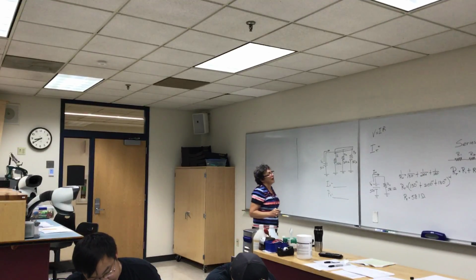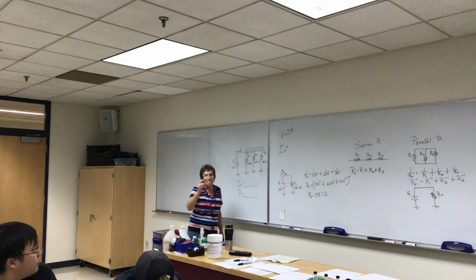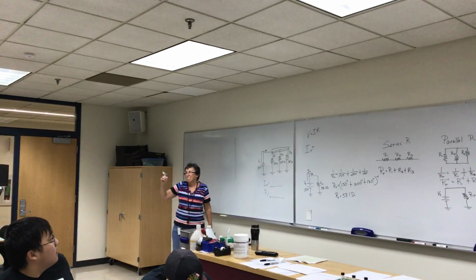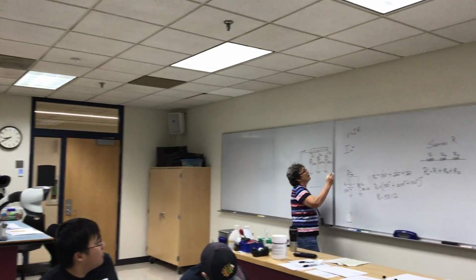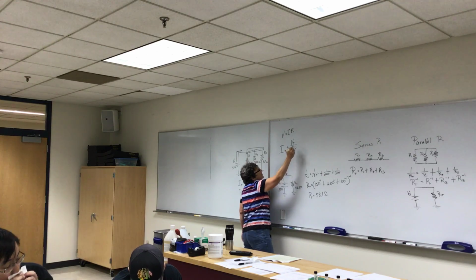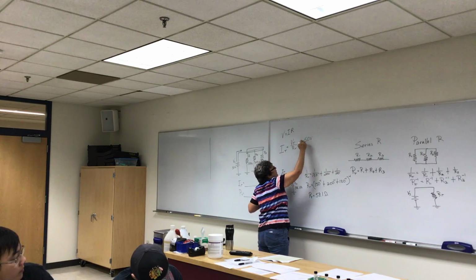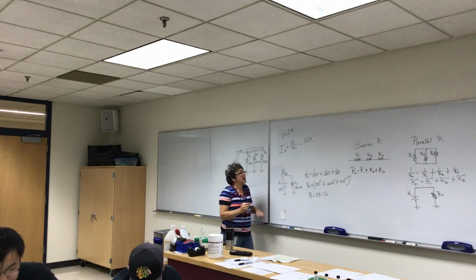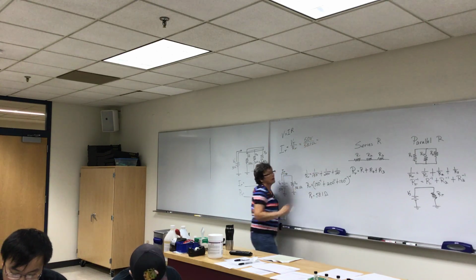What would I plug in here? IT equals what? Voltage total divided by resistance total. So it's 50 volts divided by 58.1 ohms. What's that come to?